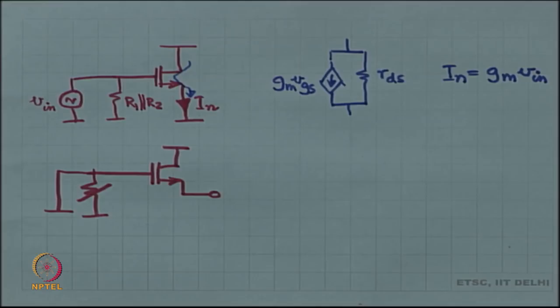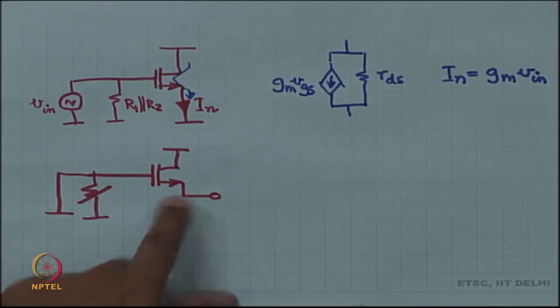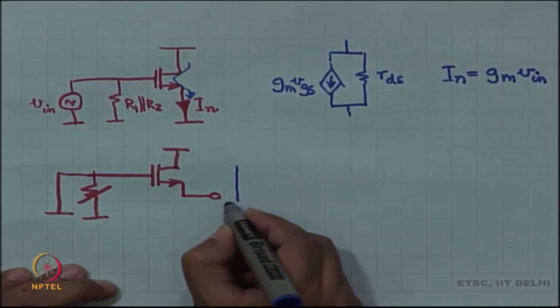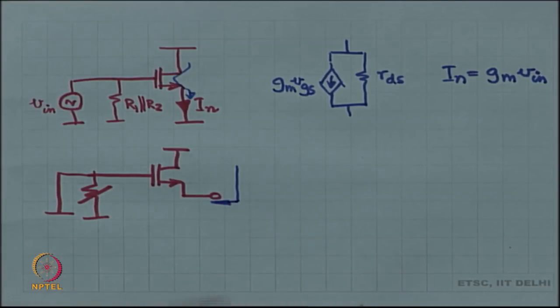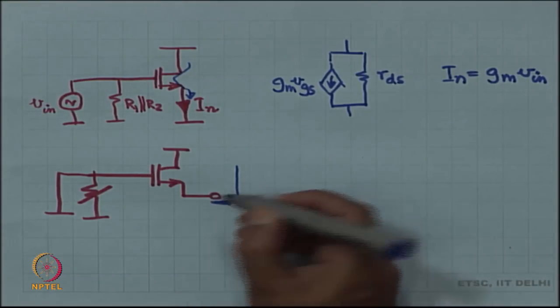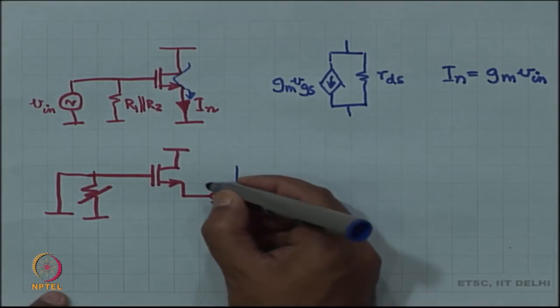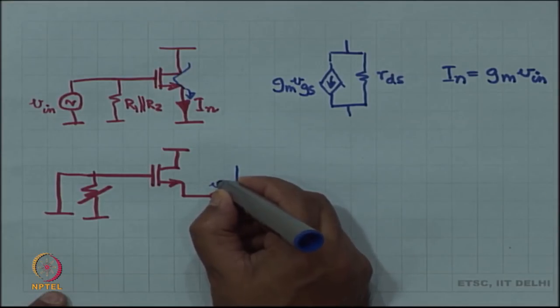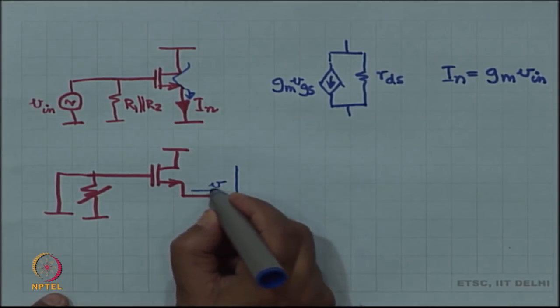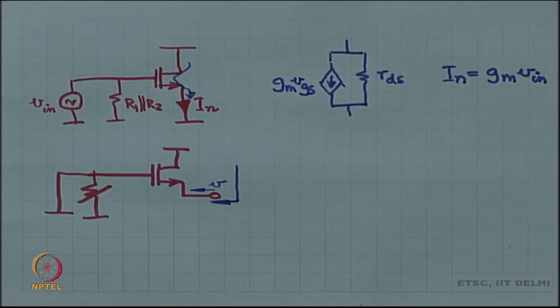And this is all you have. Once again you do not really have to draw it, but let us draw it. You want to measure with a multimeter the impedance looking in from that terminal. Or in other words, you apply a voltage of V over here and see how much current goes back inside. So, I am going to apply V and see how much current is going inside the circuit. Fine, this is the plan.